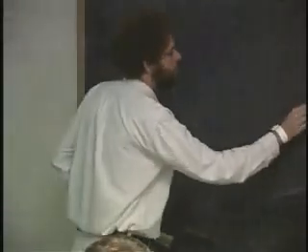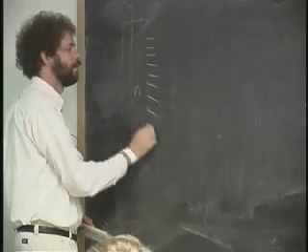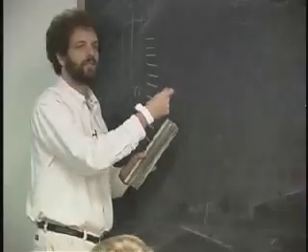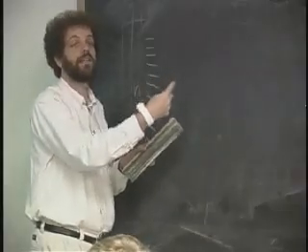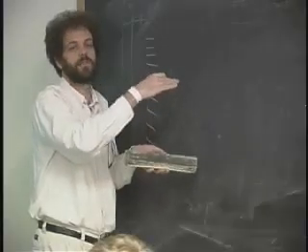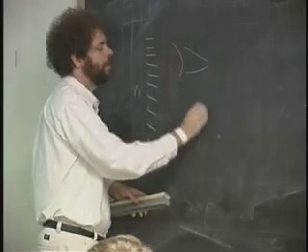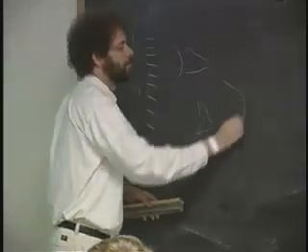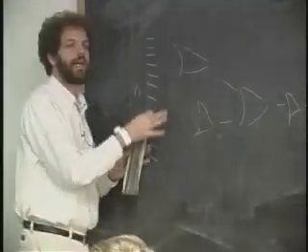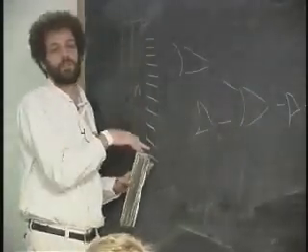How do I get from n, where n is a big number, to that 1 bit with a set of gates, each of which has a finite amount of fan-in? In other words, the number of input wires can't grow beyond a certain size. The only way to do it is to build some type of tree. I don't know what the tree is going to be, but ultimately I have to do that because I need to make that bit sensitive to all of the bits here.